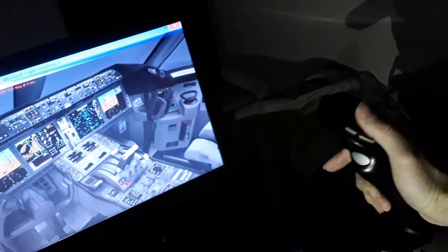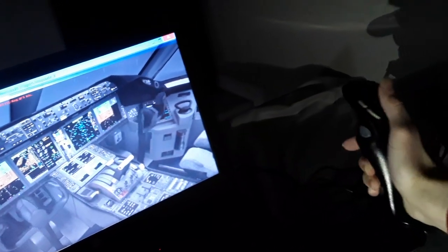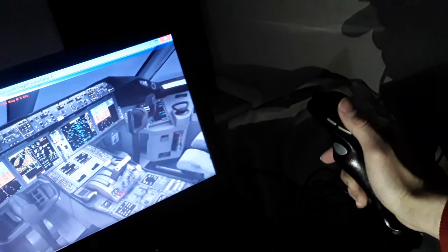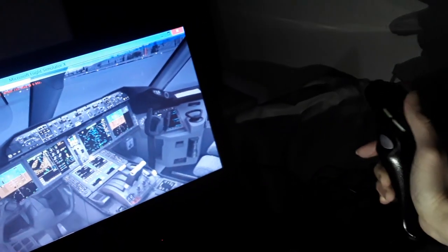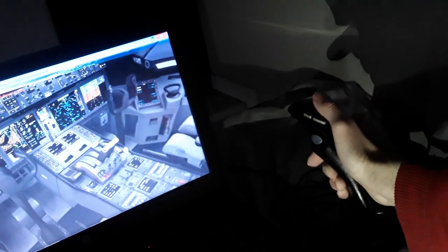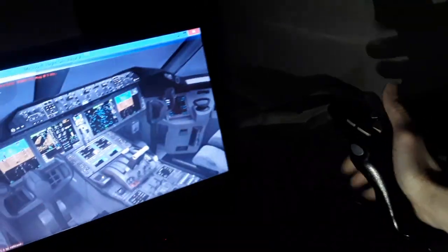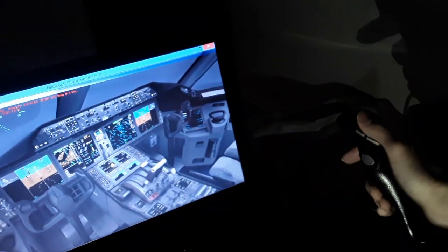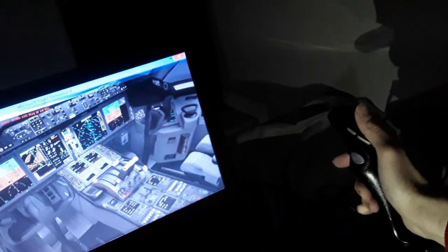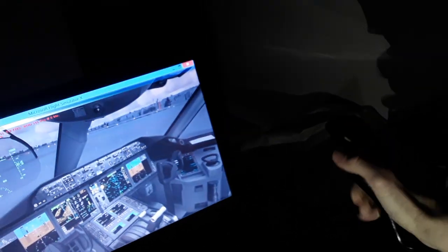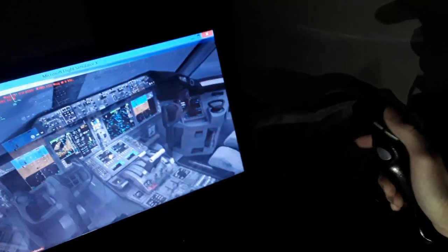So we have full flight control together, aileron, spoilers and elevator at the tail, coordinated flight controls in the air, you will see later. Also you can see the captain and the first officer in the Boeing aircraft are interconnected and move together, unless you have a failure or you want to override either side, you use some force from either side.